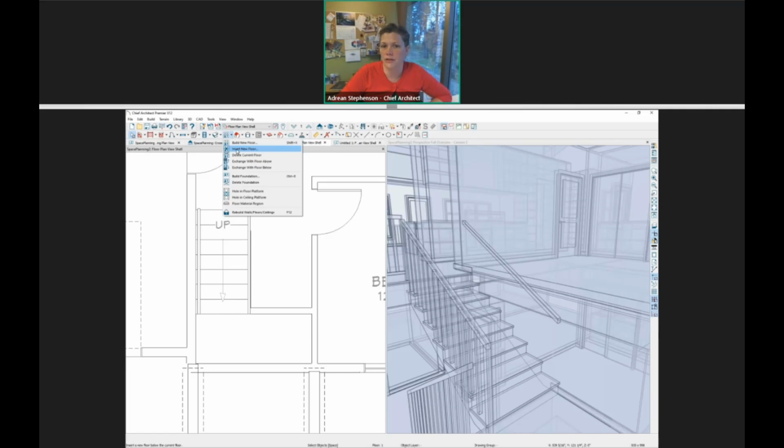I was actually trying to insert a floor below the first floor, the only kind of floor that lets me do that is a foundation. Yeah, and that's the case that I used too. So that's where I built a new floor first. I can't insert anything below the only floor. So if you built a new floor, then you can just swap them like I did. That would be a good way to do that.